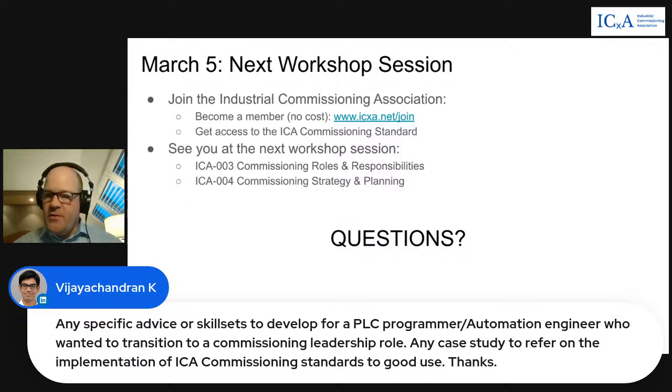So with regards to the first part of your question, any specific advice or skill sets to develop for PLC programmers? You've got lots of great testing experience, which is super helpful and valuable on projects. The next thing you need is to elevate some of those testing skill sets into a commissioning process, which is as defined in the standard. So get your hands on the standard and definitely read it, check it out, and you'll understand a lot more about what this commissioning process is all about.